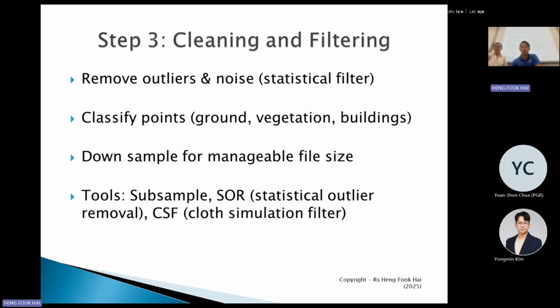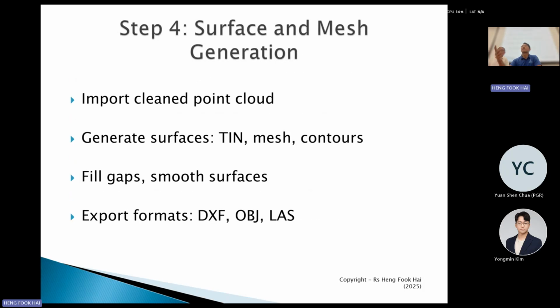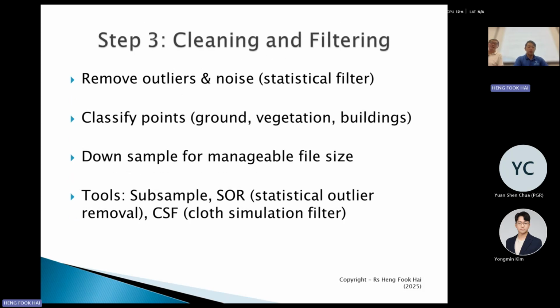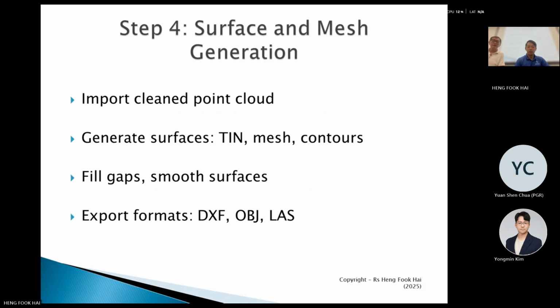And of course, we will do the cleaning of the noise and the filtering of all those unwanted data, and we do the classification of the data set to separate it out so that you can easily know what this data set represents. After all the cloud has been cleaned, we will import it into the software to generate surfaces.